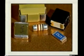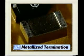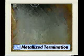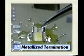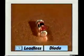The other way surface mount components are attached to PWBs is by some form of metallized termination. A metallized termination means that the surface of one or more ends of the component is covered with metal which is soldered directly to the land. These components are also sometimes referred to as leadless because they don't have metal leads sticking out from the body of the component.